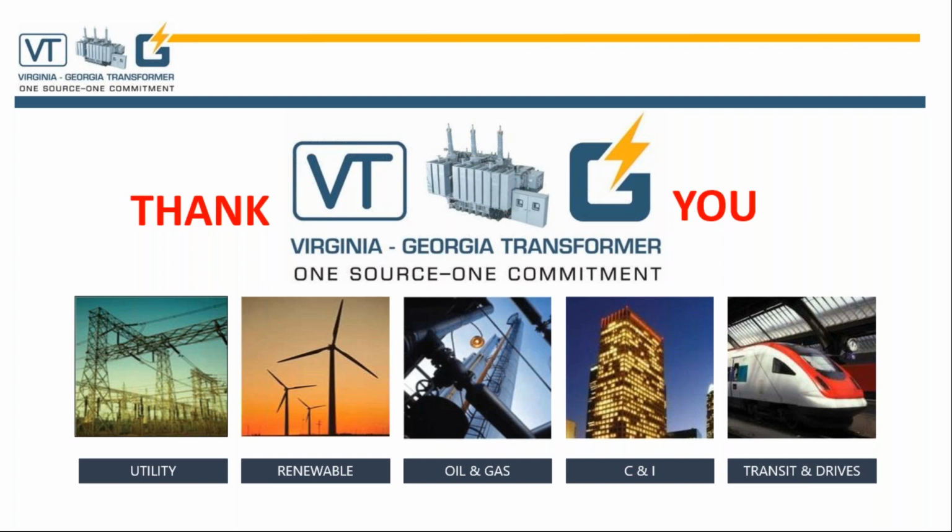Before we had these renewable energies, it was from generation to transmission through distribution to the load. But now we have additional generation stations. We used to have only one kind of generation. Now we have the traditional generation, but we also have other generations tied into the grid, such as solar, wind, and even battery stations, because they charge and discharge. So no, the answer is not the reverse power within the transformer itself. It's not from one winding to another winding. It's basically the direction of energy flow within the grid.